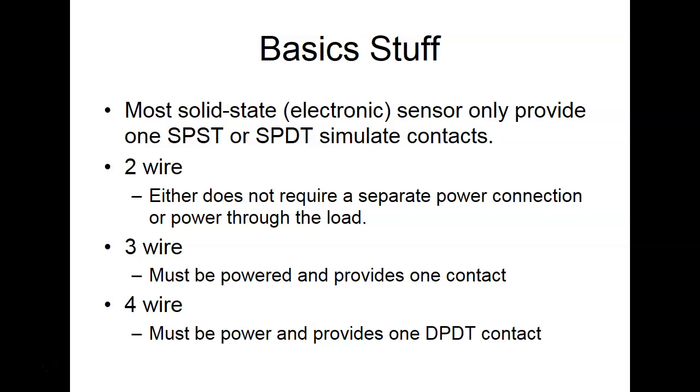If the sensor does sense, they'll drop between 4 and 6 volts. But those are going to be high voltage sources, right? Understand? So you can afford to have that voltage drop. You could not afford to have a 4 or 6 volt drop in a solid state circuit. You're running up to 24 volts, right? Okay. That's quite a bit different.